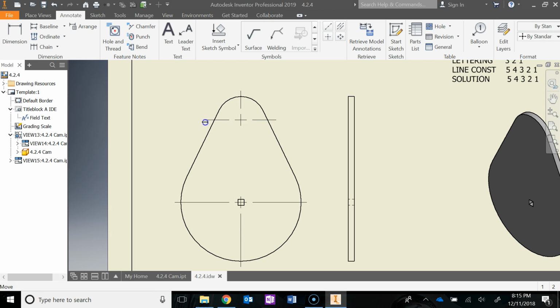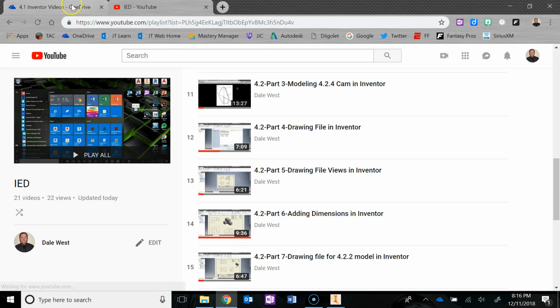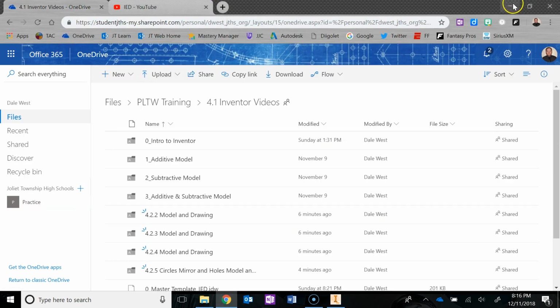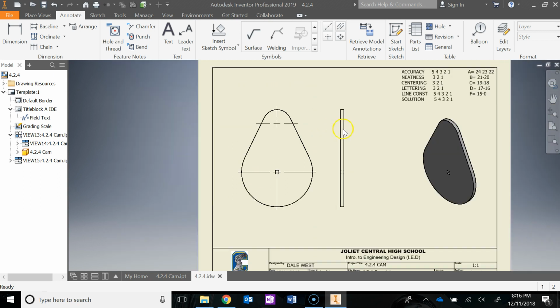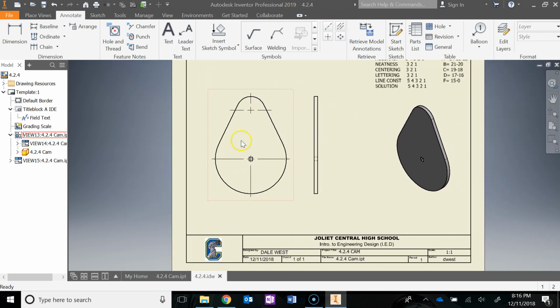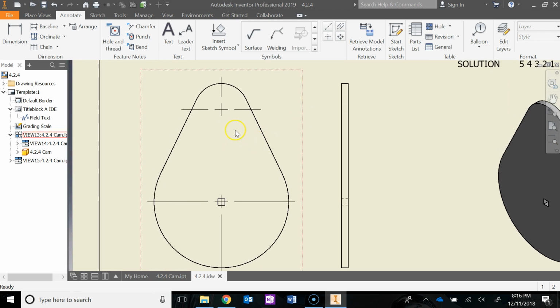So eye that up, make that look nice. So we adjusted that one. Now, if you remember from the model, they had a center line connecting these two circles. And that's actually how I knew that we should add that vertical constraint, because the center of this circle is vertically aligned with this circle. So we need to connect a center line from there to there.